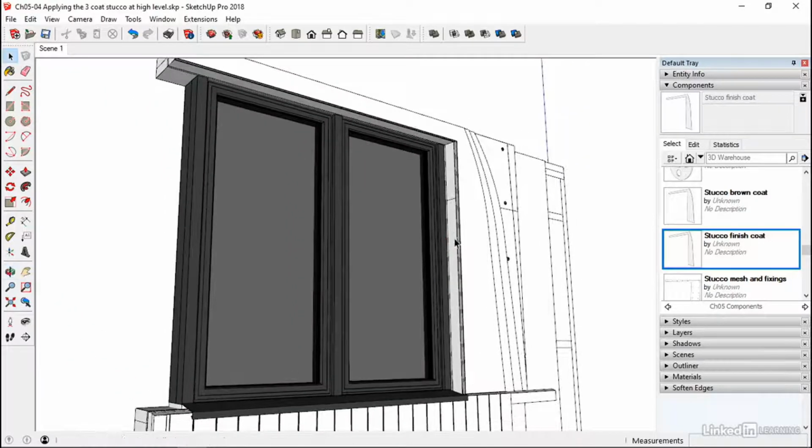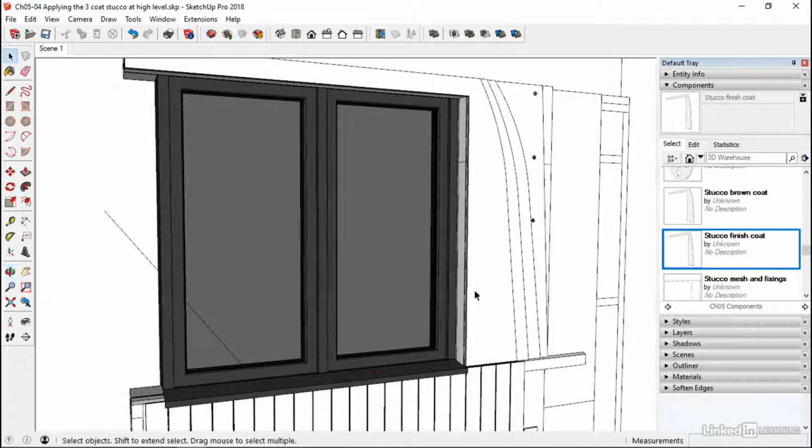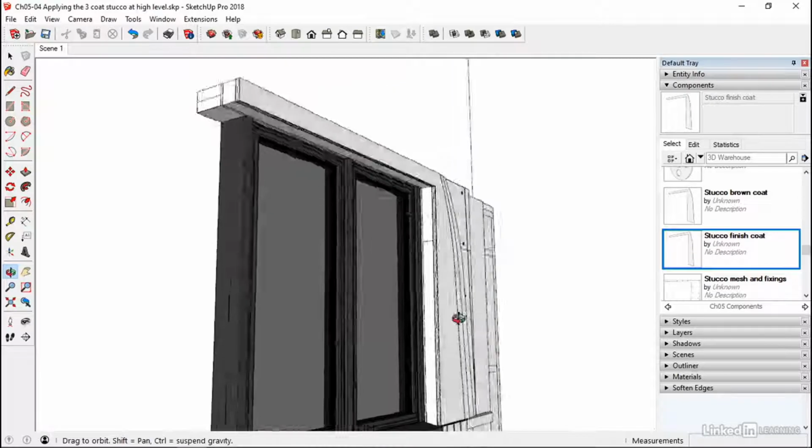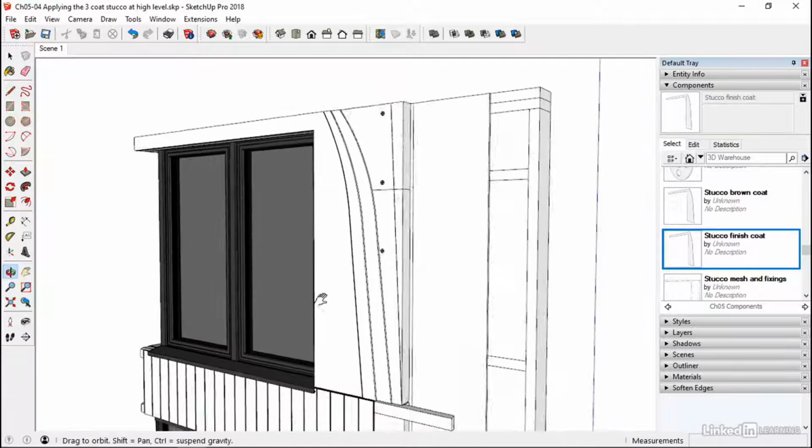Okay, in my case, I've got flashings that clip in to this, so it gives us a neater finish and replicates what we've shown the client on the original one, where this whole area is dark bronze. So that's why I'm doing that, but you could put a little angle bead around there so you can sort of finish up to. This is a wet trade. So this is not a board finish. This is applied with a trowel and then finished with a specialist sort of craftsman's job, that one.